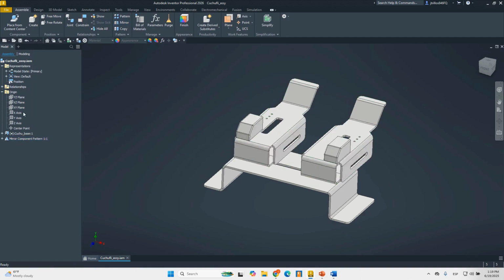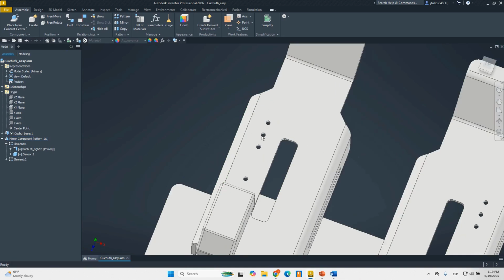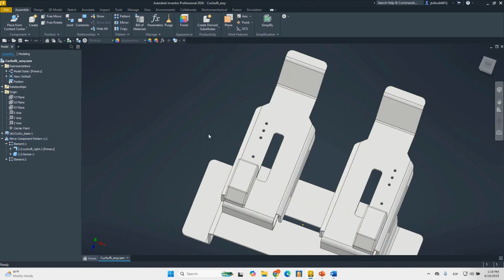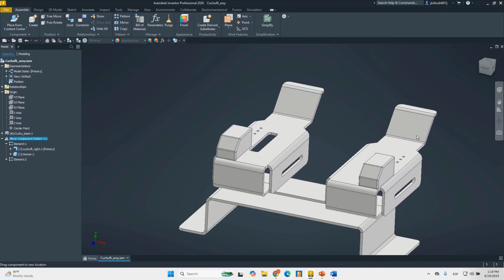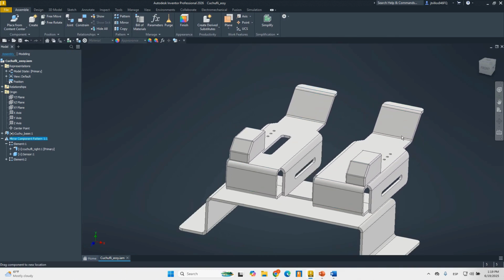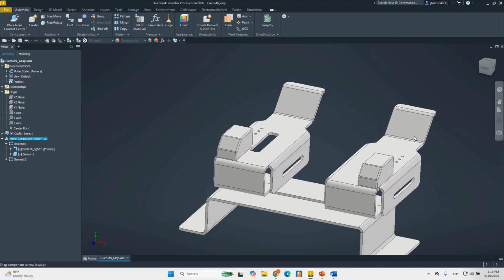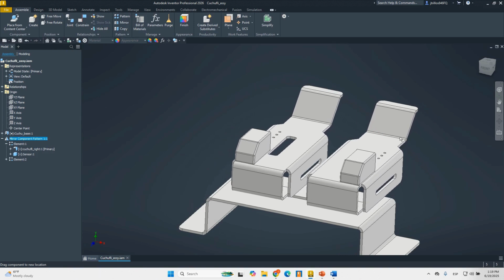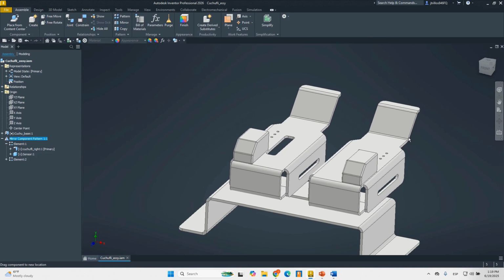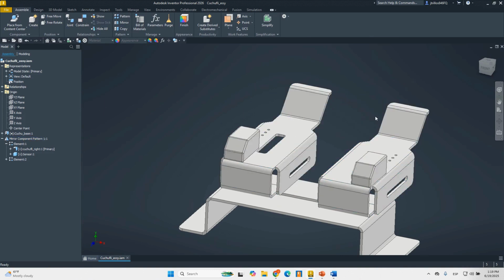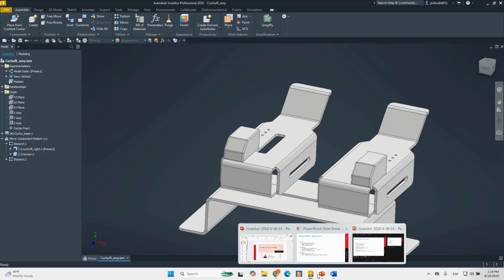Okay, what I'm gonna get now, it's a pattern. Okay, so Inventor is going to copy the elements, right? It's going to mirror the proper ones that I select. It's going to reuse the ones that I want to reuse. And it's going to create the association automatically between the two, okay? So I don't need to worry about creating the relationships again. I don't need to worry about creating constraints, joints, or anything, okay? Inventor is going to take care of all of that.